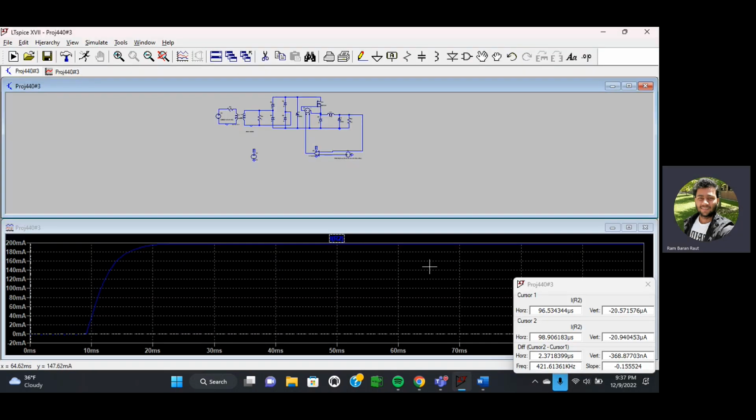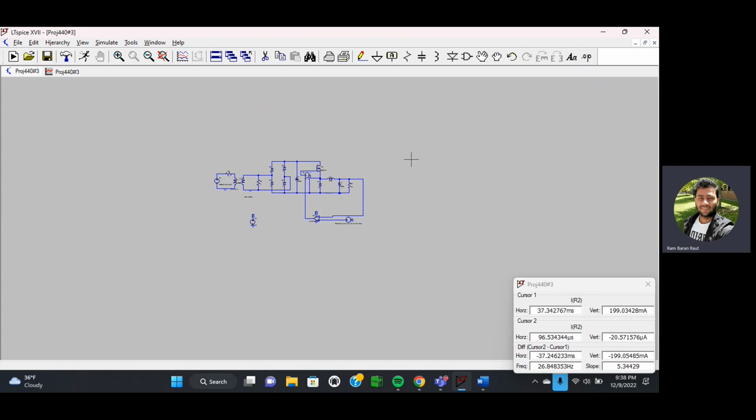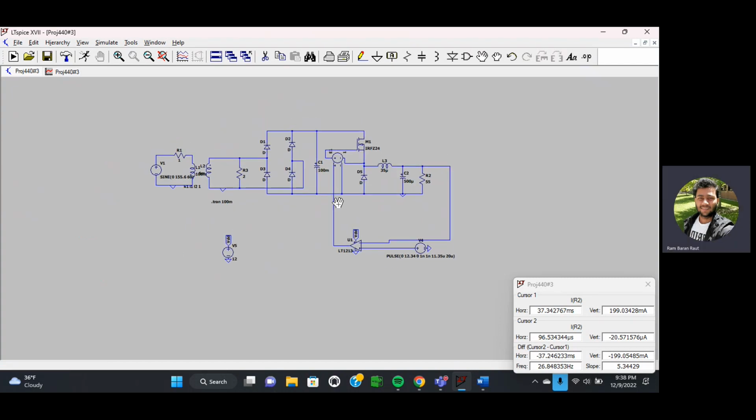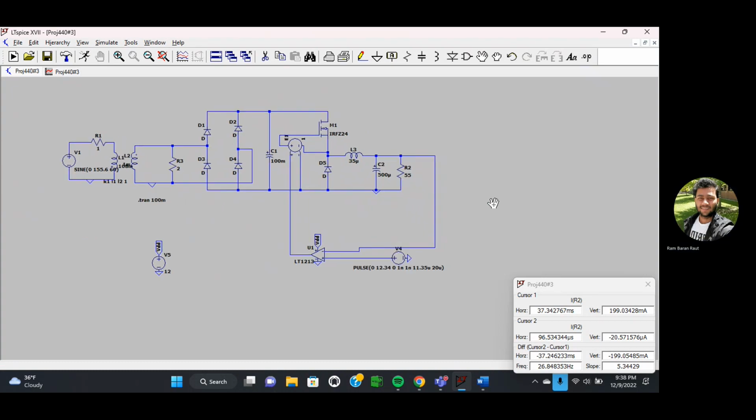And let me go over LTspice. So right now, how much do we have? We have 199 milliampere, which is almost 0.2 amperes. So we are getting this. Now let me make this one bigger. Let me move this part over here in the middle. And now we can make it bigger. Right now I have some 55 ohms. So I have this, and now I'm going to change.